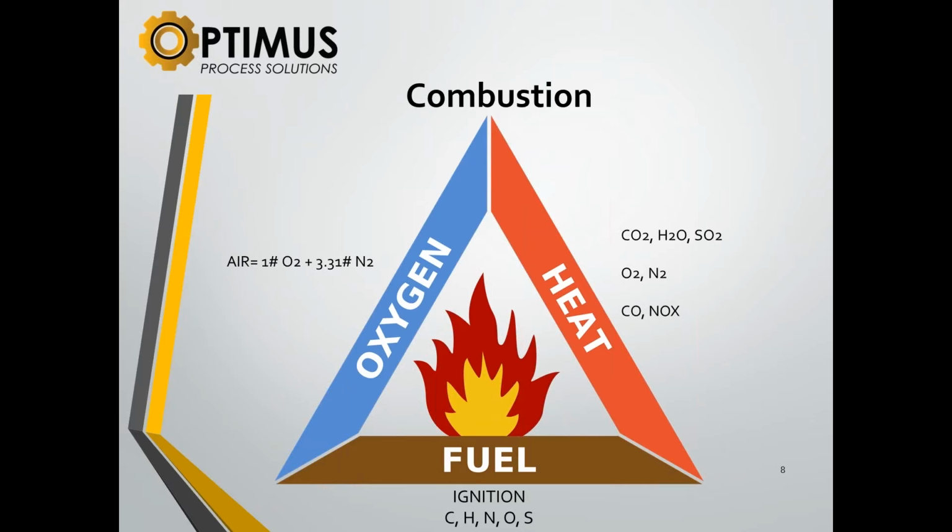And if you put excess oxygen in, more than you need for the chemical reaction, you'll wind up with some oxygen and nitrogen. And nitrogen is something that, using air as the oxidizer, you get, for every pound of oxygen, 3.31 pounds of nitrogen free. I see. Useless nitrogen. It doesn't carry any heat or anything. It doesn't do much. All it does is consume heat.